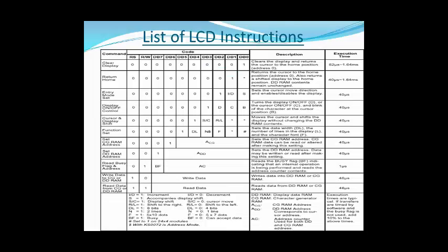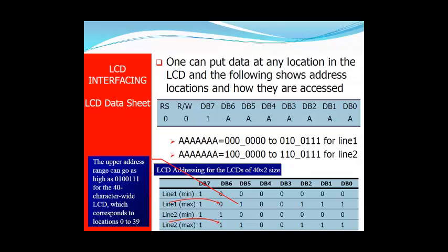This is a list of LCD instructions with their command codes, their description, and their execution times. One thing to be noted here is that execution times are typical. If transfers are timed by software and the busy flag is not used, we have to add 10% to the above time. Now the LCD datasheet.